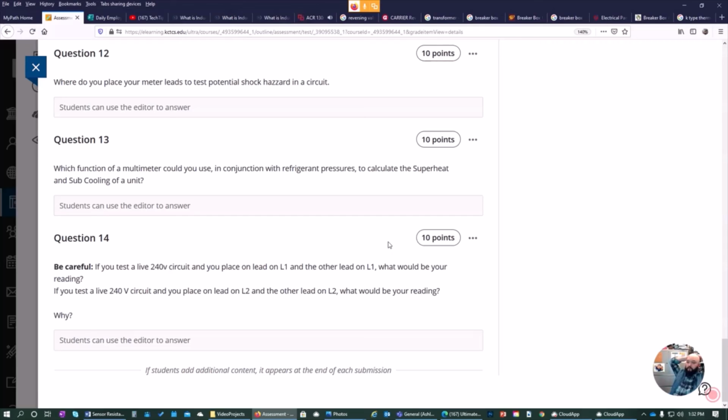So for example, what's the best way to know if a resistive heater is running? Do you know? You put an amp probe on it. 5 kilowatts, it pulls 20 amps. At 10 kilowatts, it pulls 40 amps. 15 kilowatts, it pulls 60 amps. You can tell if all your heaters are running by doing an amp draw.